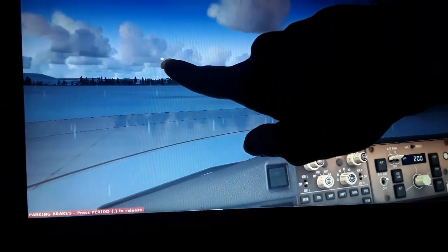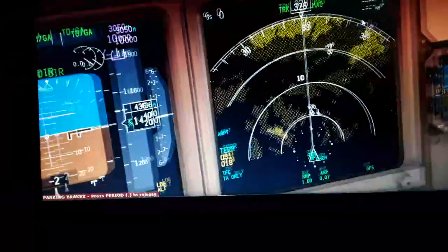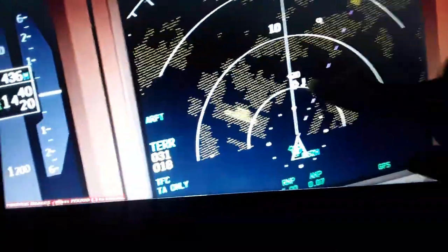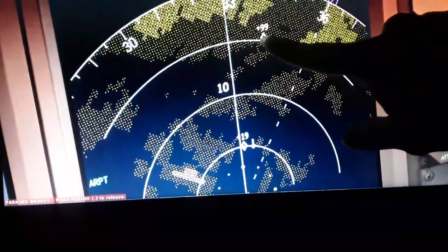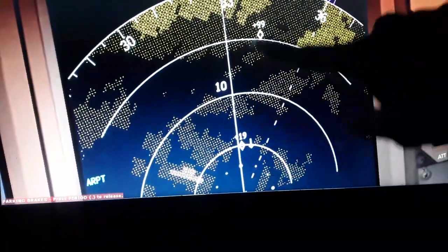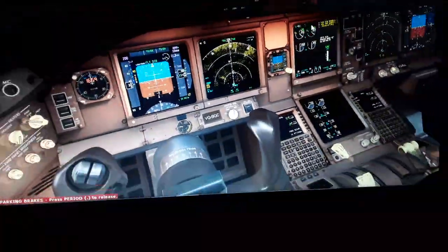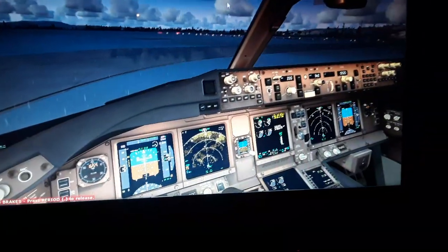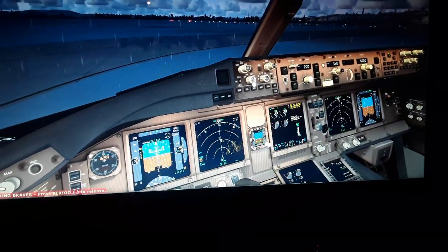We just spotted one aircraft is coming closer to us, so we will follow that in the navigation display. Over here is plus 2,000 feet. The other is 15 nautical miles away, is farther away. So you can see both aircraft plus 1,100. It's closing in. Now it's plus 5 nautical miles away.